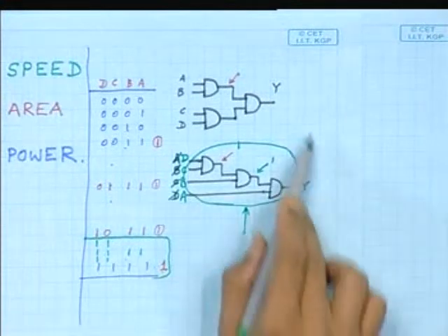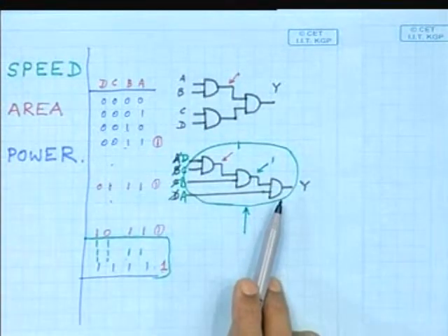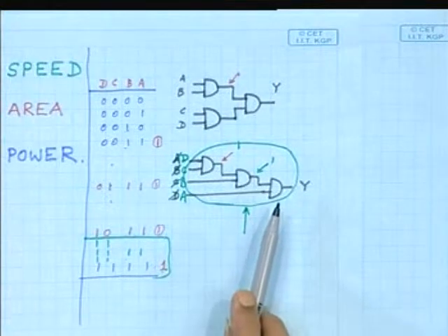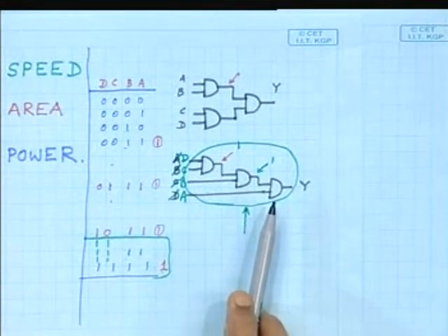At what level? Whatever we have been discussing, can we identify at what level we are talking? That is logic level. Gate level means it is basically logic level. Now at different levels, say at transistor level also, you can think of saving some power. Even at the architectural level, whenever you are reducing the total number of operations, that means you are saving power, because if you can save some computation, you can save some power which would otherwise be burned for computing those things. At the architectural level, whenever you are saving some register or counter, at that time also you are saving some power.